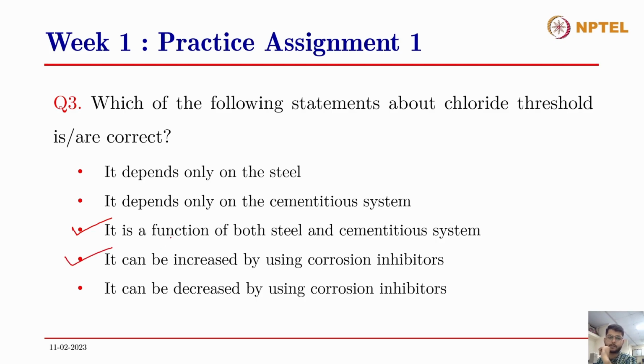Also, can you tell me what is chloride threshold and how it is related to the deterioration of concrete or steel? The extent of chlorides which can be borne by the system before corrosion is initiated. Once it is initiated, then it's very difficult to stop the process. That level is probably the chloride threshold. Okay, right. Thank you, Dr. Satish.